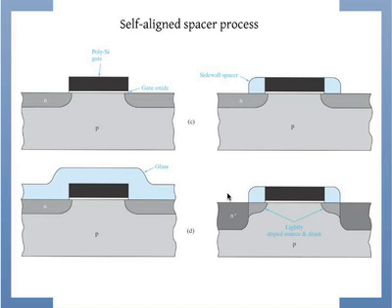boron. No, wait, phosphorus. I'm always thinking. So you implant phosphorus to make this N+. Of course, making the source and drain N+ means getting a better ohmic contact to the metal. Right? That's the reason to do that. Okay? You still leave a lightly doped source and drain region right under the oxide. The oxide will prevent the phosphorus from going through.